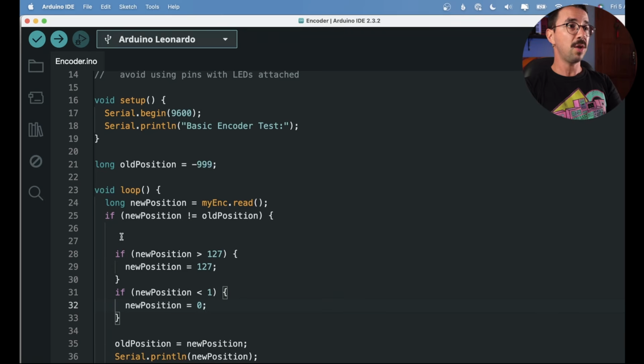However, there's another thing we need to do here, that there's a function running in the background when we move the encoder. And that function is increasing and decreasing the number -1, -2. It doesn't care if I'm restraining my new position variable, because in the background, it's going on something else with another variable. So we also want to restrain the variable that's been used in the background.